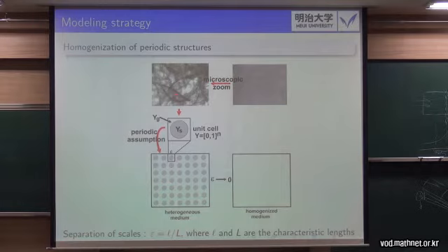And even at this stage, we still have a problem, because what we are trying to do is, in this sort of media, to impose reaction diffusion equations that describe the process of interest. But we cannot do this in this medium because for smoldering combustion, the reaction only takes place at the surface of the solid.